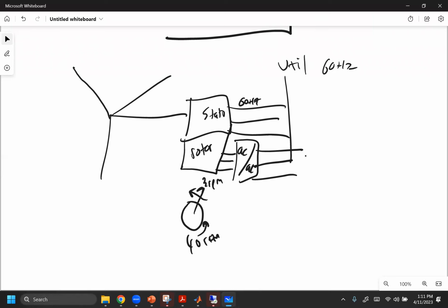Yeah. So I'm assuming on an induction motor, even a doubly fed one, if you shorted all the windings together, it's still going to let it spin. Yes, it would, but the stator windings wouldn't last very long because they're not designed to handle that amount of current. Just like on your permanent magnet motor, right? If you actually shorted the stator windings, you would have more current than what it's designed for, and you potentially would burn it up. You can short our motor or field windings and not have any issues because you just have magnetic fields there. They're used commonly for like just parking brakes.